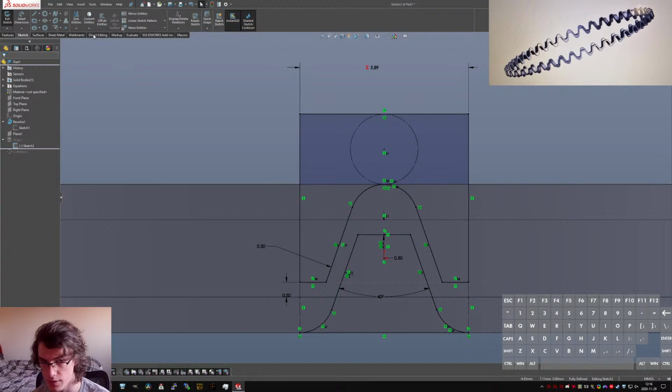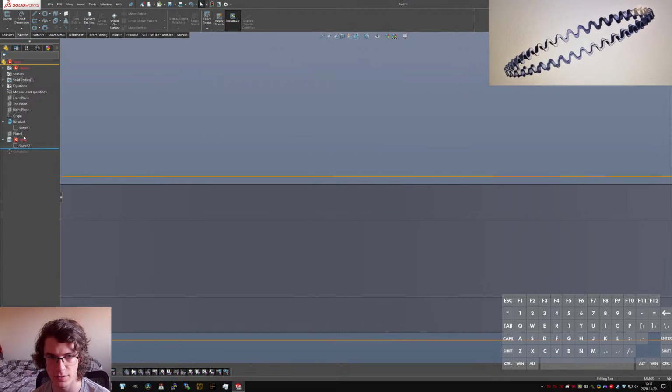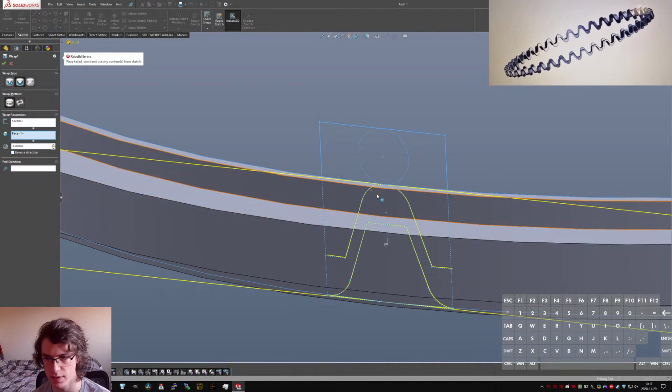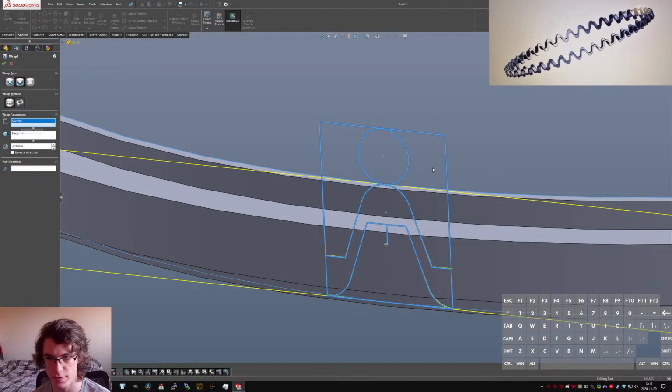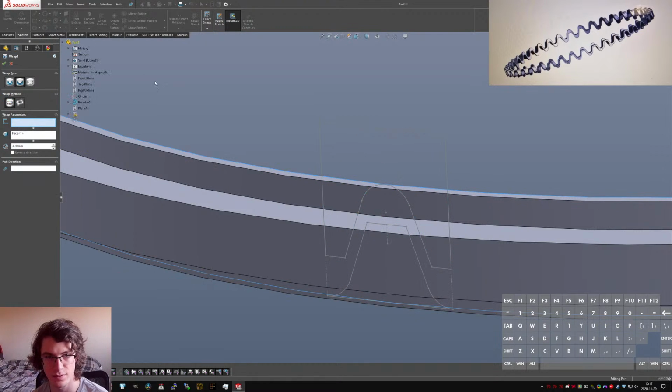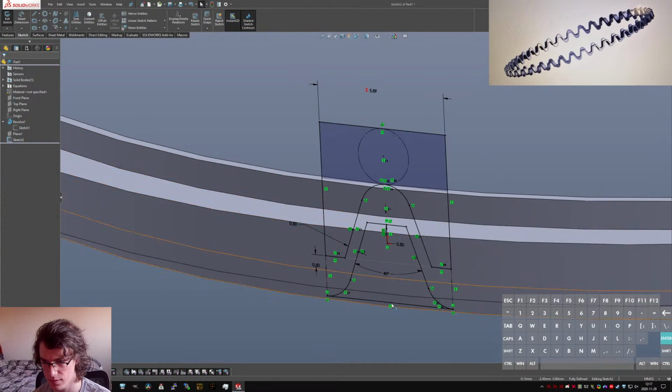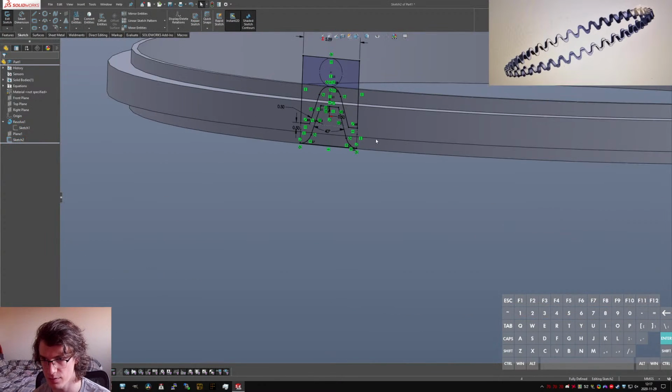Yeah, that's pretty good. So the first thing that the wrap will do is it'll throw a fit because, oh, hang on. Could not use any contours from Sketch. Wrap parameters. Not great. Source Sketch. Won't let me select that. Okay, so I'm going to have to undo that. I'm going to have to reinspect this sketch. Yeah, it looks like I only have two closed contours.